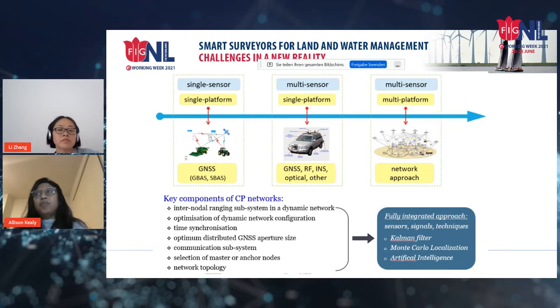There are certain environments where no amount of signals from satellites, no amount of new constellations going up, are going to overcome the limitations. Urban environments, underground tunnels, underwater. And so the shift has been to looking at the sensors that can be combined, where we do sophisticated error modeling. We look at the uncertainties and balance the strengths and weaknesses of different sensors.